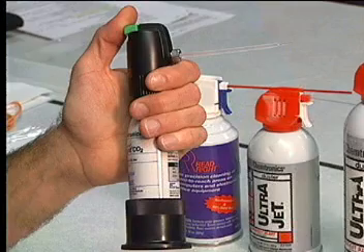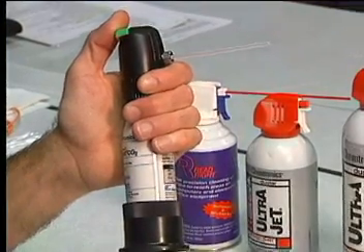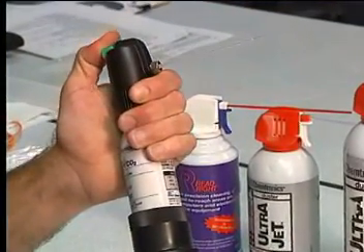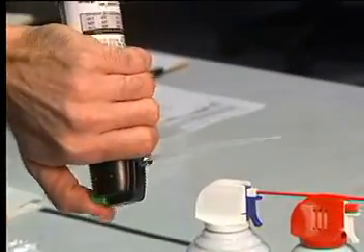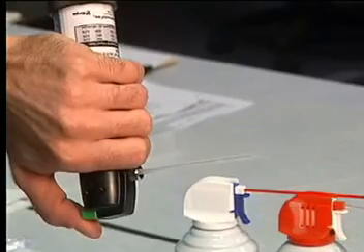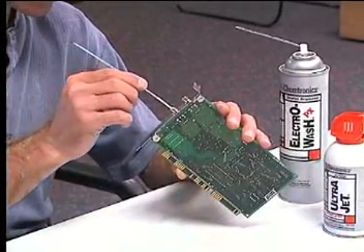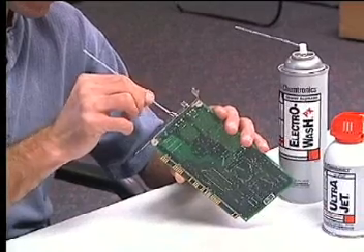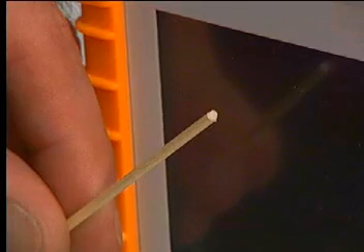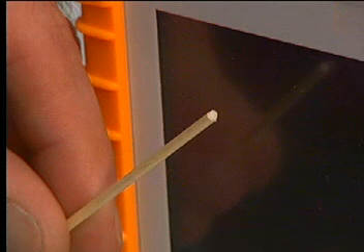This duster uses high-pressure carbon dioxide gas in place of a liquid propellant. This duster can be safely used in any position, but costs much more than conventional dusters. After using the duster to remove any large particles, the optical surface can be cleaned with a swab. This swab is designed to clean optical surfaces at the end of a coupling sleeve. It consists of a wooden handle with a small button of adhesive foam at the end of the swab.